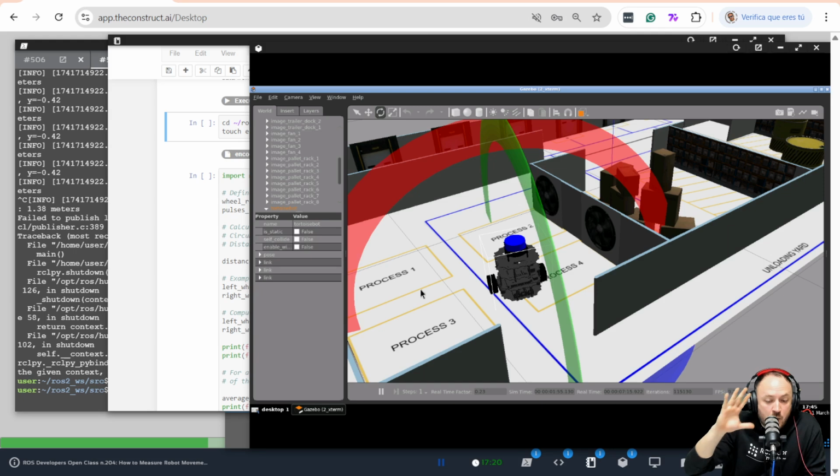It would be an omnidirectional drive, yeah? Or also known as holonomic. That is another case, and that would use different formulas. Here we are assuming that the robot is differential, so it can only move in the x-axis and rotate in the z-axis. Yeah? This robot cannot move alongside the y-axis directly, because that would require a holonomic movement. Okay?